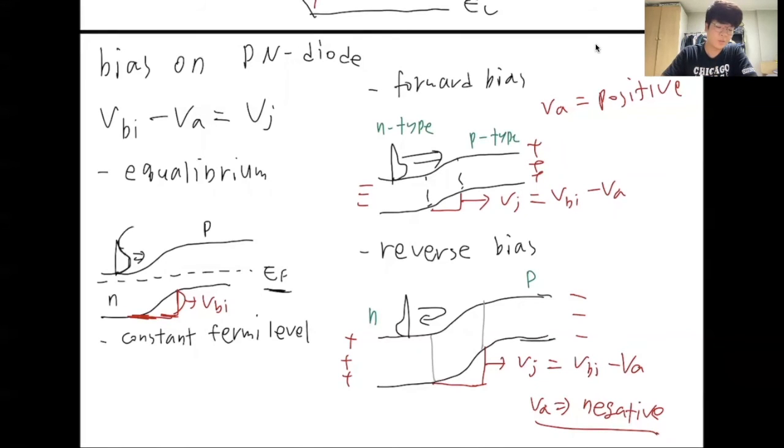This Boltzmann tail means the concentration of electrons, and there is a slope, which means that there is a built-in voltage. If we apply a forward bias, with negative potential to the n-type and positive potential to the p-type, then the junction potential is lowered so that electrons and holes can pass through the junction.